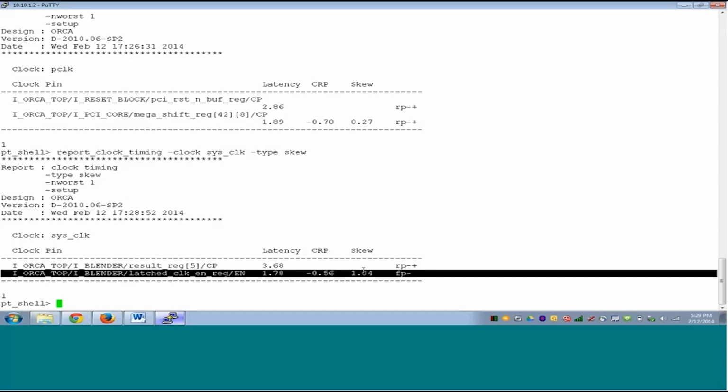Usually, if there is a clock that is generating a clock, and if it's balanced with the rest of the group, it will have a very big latency. And always we want to keep the clock latency lower. The lower the clock latency, the better is the timing because of the OCV effect. You have to understand this. Consider this. Give some thought on this.